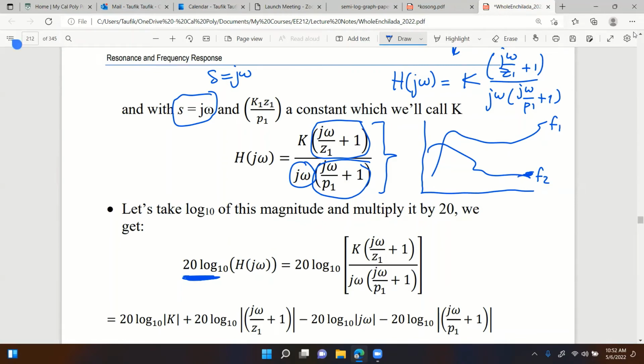And then will that be difficult if you have to divide or multiply the two functions? The operation that you have to perform for the two functions in order to get the actual plot of the transfer function will be multiplying or dividing. You see this? Multiply or divide. That will be a difficult operation to do, right? Would that be easier if I just add the two? This is the benefit of using log scale. Just watch. What happens after I take 20 log of this transfer function? What happens after I do this?